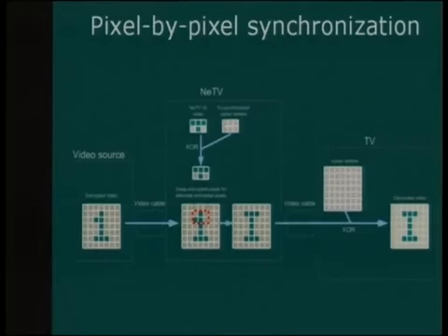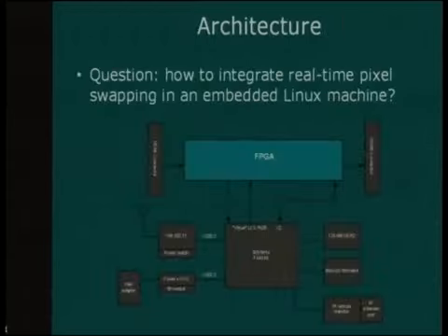So at the end of the day, if you had this sort of encrypted video coming from the source, you have your unencrypted video in the frame buffer, you have your cipher state here, you hash them together, XOR them together, and then you can just go ahead and swap those pixels out when they're decrypted. You can turn a 1 into an I on the screen.